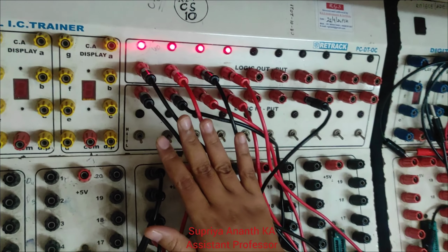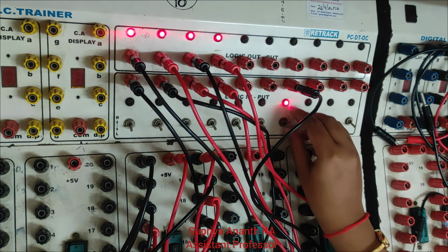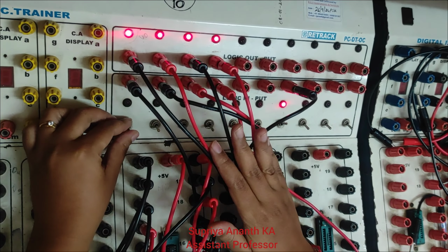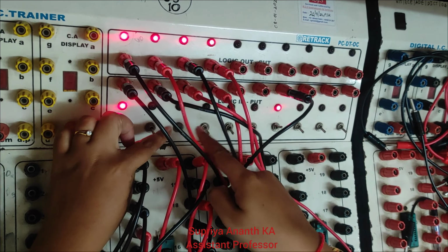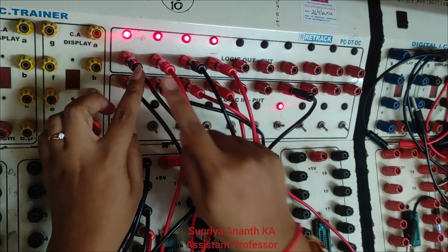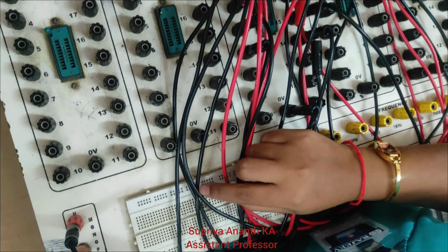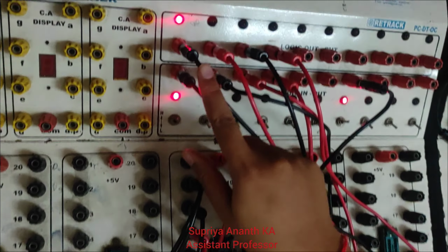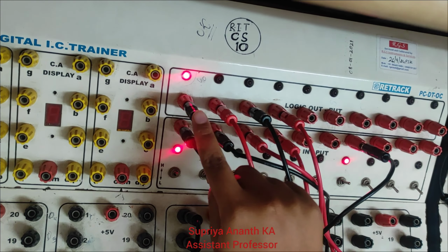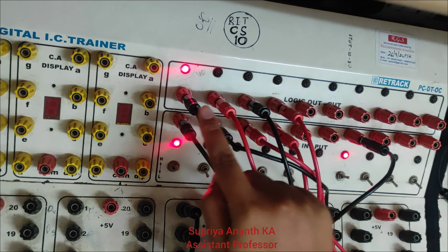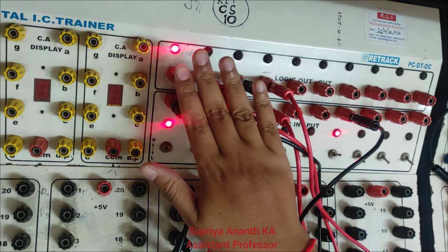In order to verify the circuit, first we need to activate the mode here. Once the mode is active, I am going to provide the parallel input. Here I am going to give 1 0 0 0 as the parallel input. The same has to be reflected as output, so I need to press the clock pulse. Once the clock pulse is pressed, whatever input I have given, 1 0 0 0, the same is reflected across the outputs QA, QB, QC and QD. So the value has been stored.